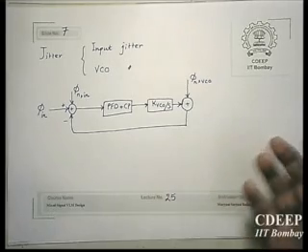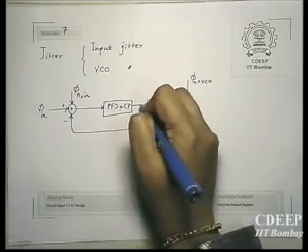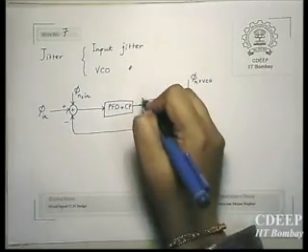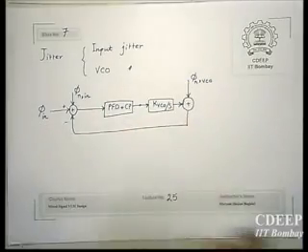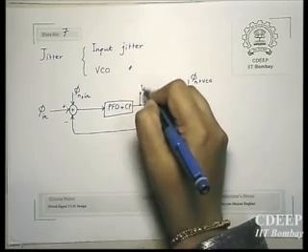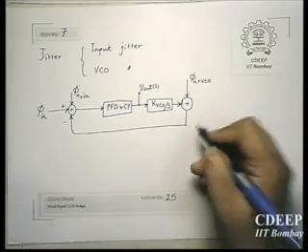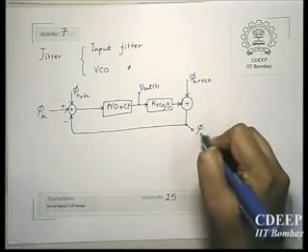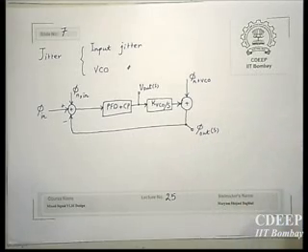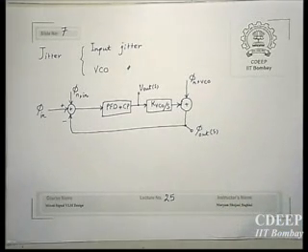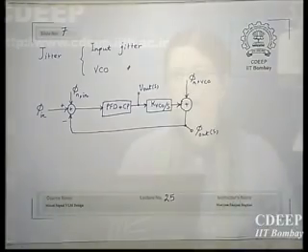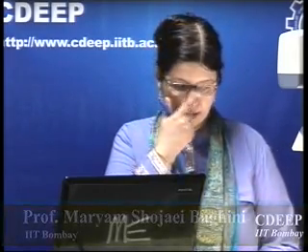If you look at the transfer function of the system with respect to input phase noise, it's the same as phi in, because they are just added. So it's the same as before, that we know. Therefore, the bandwidth of the loop with respect to input phase noise is determined by the bandwidth of the loop that we had before for V out or for phi out. So the same consideration means that the bandwidth should be low enough to avoid any kind of jitter and phase noise. So we should be aware of this.